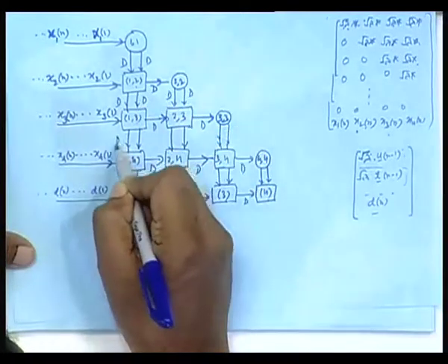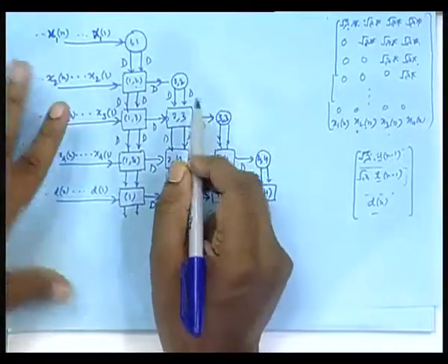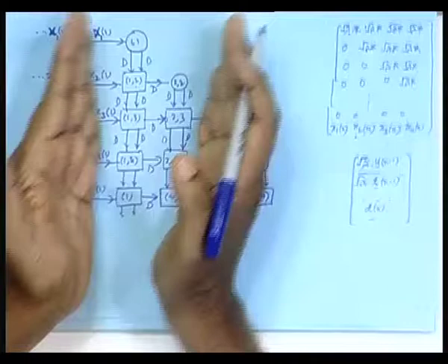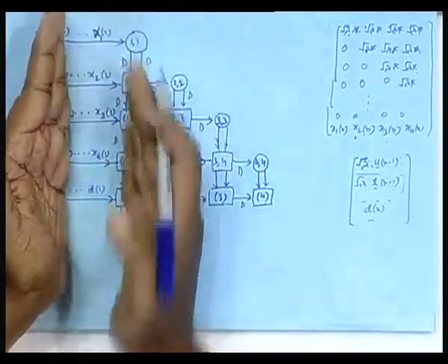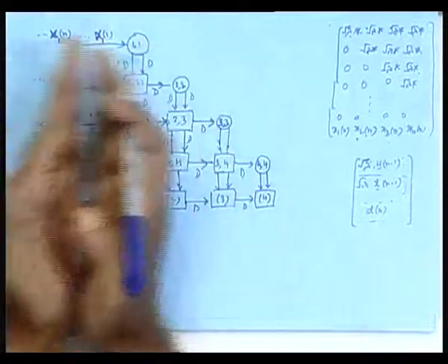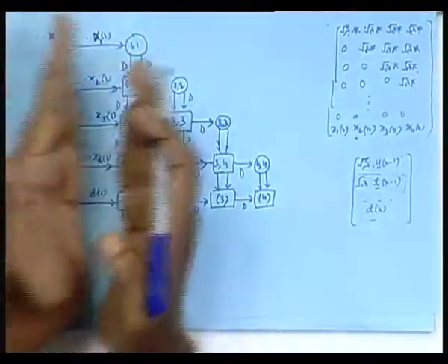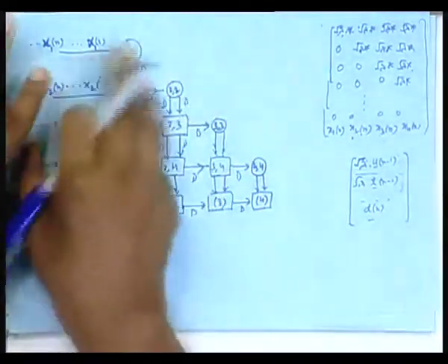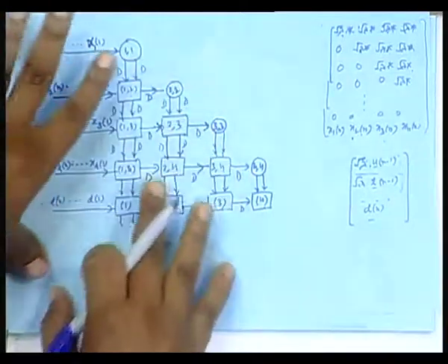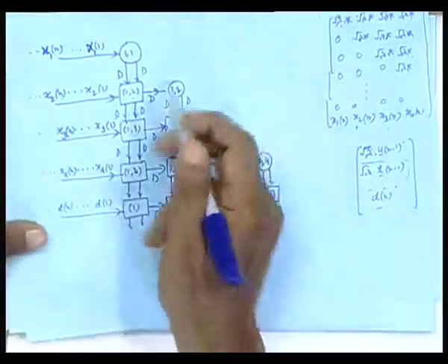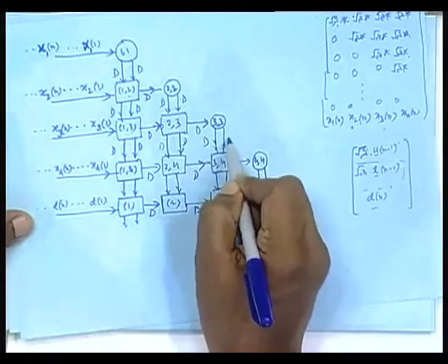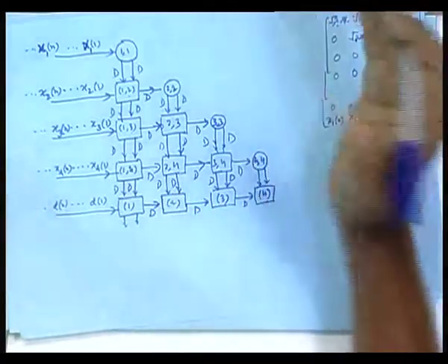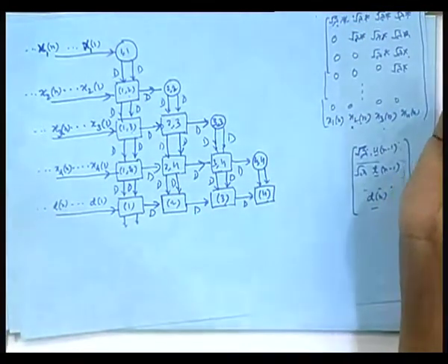with the same logic. Then you take it as a home task to see the sequencing of data, how the data moves through the array. Here, when it was only horizontal, in one cycle, all the processing, then next cycle, that output moves here, and x1 n+1, x2 n+1, they come together, they move here. But here it will be a little delayed in both ways. So, that sequencing, the data movement, you just have to work out which data goes where. Okay, but D. Correctness will not be affected. You can verify that.